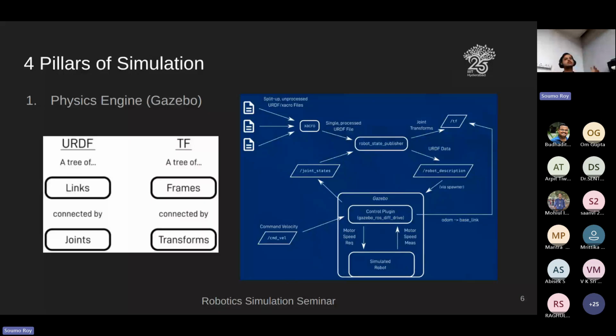So this is written in a particular file format called Xacro files, which consist of the data of these links and joints, and URDFs that would go more towards the robot state. And then we would try to broadcast different kinds of transformations for the robots. And this goes into our Gazebo environment, where I'm going to simulate my robot to show you how different components of a simulation are going to bridge in.